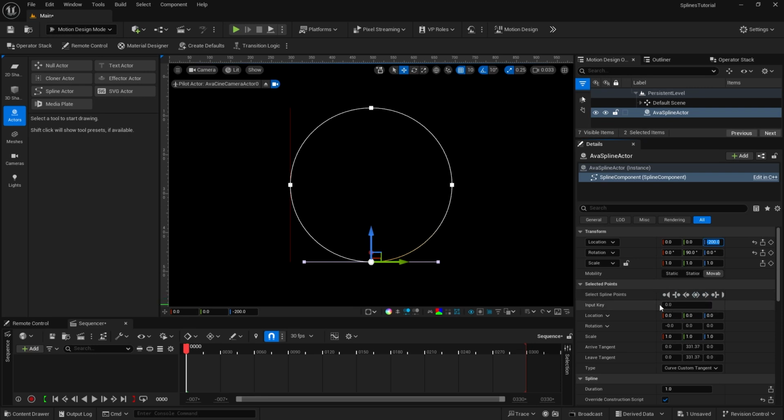Right now, we're on input key 0. It starts off at 0, then it'll jump to 1, 2, 3, and 4. But we're right back at the location we began with. If I click one more time, we're back at 0. So that actually means that there's 5 points in here and I only want 4. So what I'm going to do is make sure I'm on that 4th point right there. And just to show you this, I'm going to drag that off to the side, bring it up a little bit. You can see that we have 5 points and also that this is not closed.